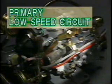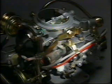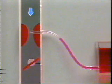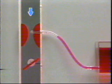The primary low-speed circuit supplies the air-fuel mixture when the vehicle is idling or traveling at low speeds. Here we will use a model to demonstrate. As you can see, the throttle valve opening is very small when the vehicle is idling or traveling at low speed. The amount of air allowed in by the Venturi is small, insufficient to draw much fuel.